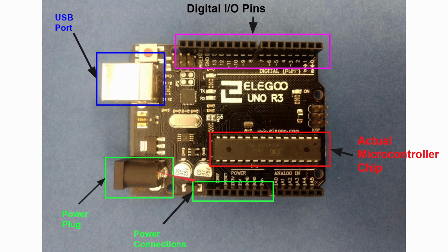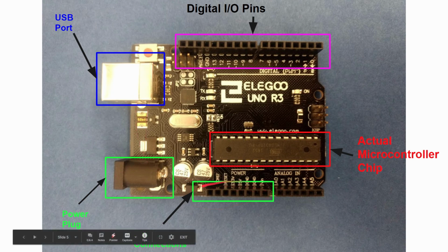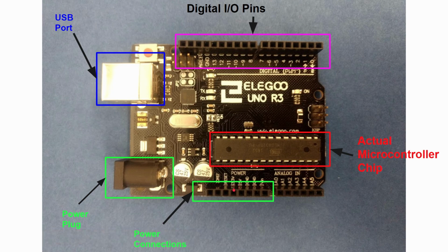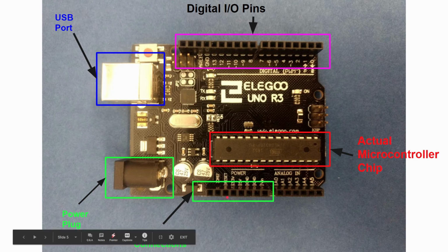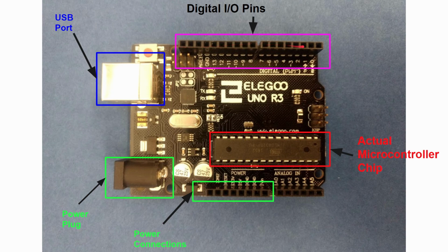We've got some connections over here called pins, these little squares right here. The pins in this section are for power. It's hard to see the labels, but this one's 5 volts, this one's 3.3 volts, and this one's ground. We've got a few of those here. And then to communicate with other things, we've got the input-output pins over here.